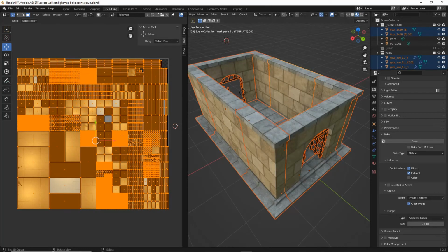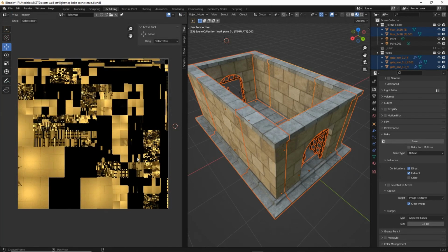And that is our light map. So if we've done this correctly, if we set all the objects up and the scene up correctly, the baked light map won't influence any of the other objects that are in the scene. So that's the way to check that the objects are set up correctly for light mapping. But once we've got our light map, we can then save the image.